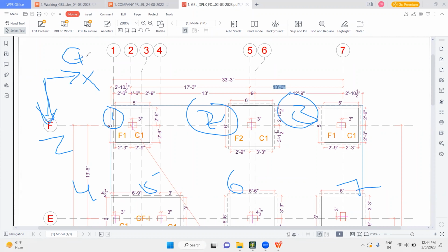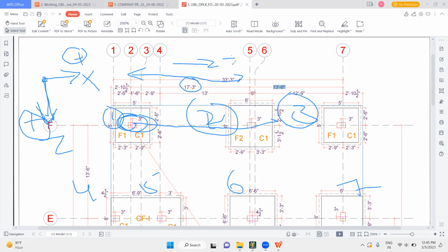This refers to the positive direction, and this also refers to the positive direction. If you want to create a node here, this is exactly the 0 point, so we have to create a node exactly at 0, 0, 0. Then we are going to copy and paste it here with a distance of 17.3 inches, which means this way. Since it is this way, it is the positive x direction. So copy and paste it in this direction, which is again the x direction.